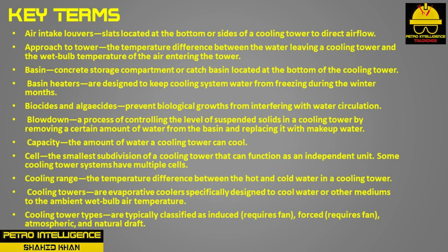Air intake louvers are slats located at the bottom or sides of a cooling tower to direct airflow. Approach to tower is the temperature difference between the water leaving a cooling tower and the wet bulb temperature of the air entering the tower. Basin is a concrete storage compartment or catch basin located at the bottom of the cooling tower.